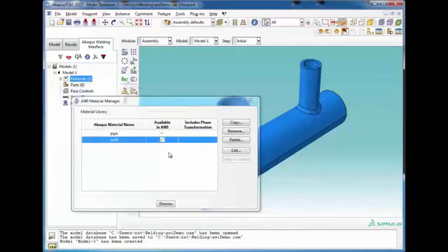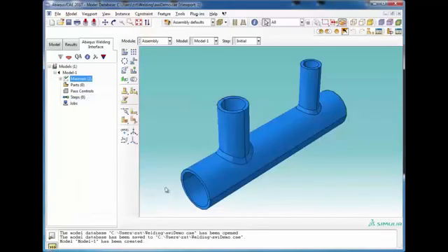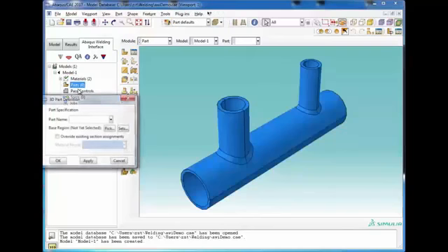All right. Now we've made these materials available. This third column is whether these materials include phase transformation. There is a plugin that allows us to use phase transformations in our materials. It's a separate UMAT. So the AWI is linked to that plugin, but we're not going to use it in this case. So you see now that we've modified a couple of materials, we at least have something that we could use inside the weld model. So we see this green check indicating that we can move to the next step.